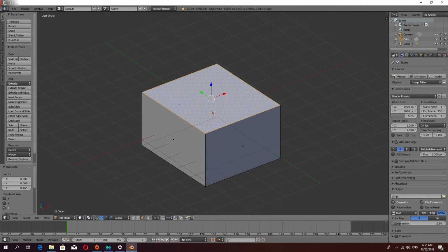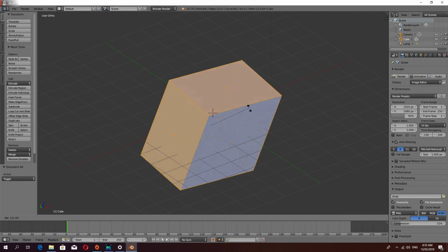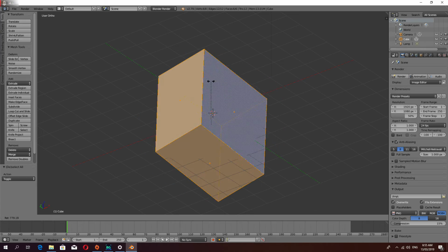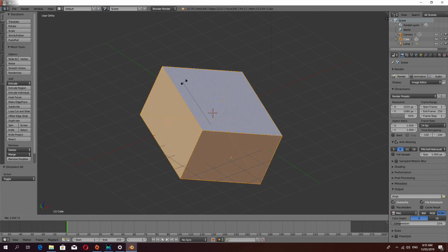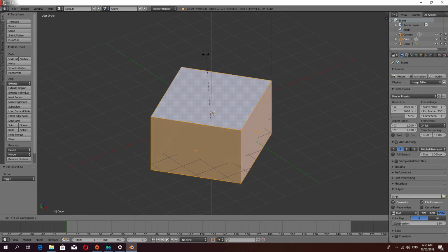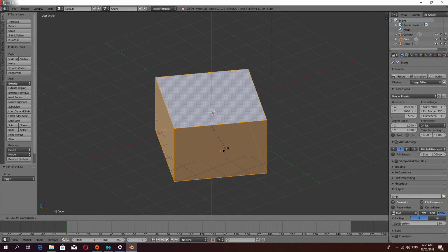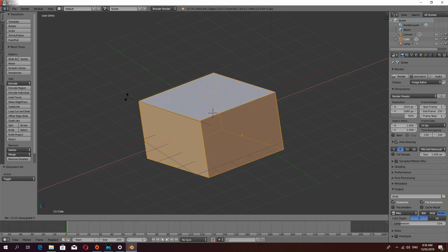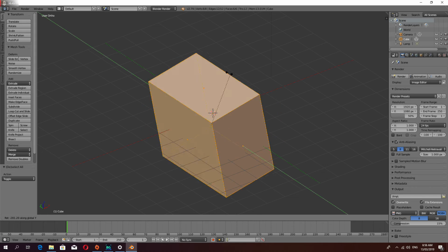And it's the same with rotation. Let's say I select the whole thing and I want to rotate. Rotate is R. Well, currently the rotation is kind of weird. It's done via the viewport, so it rotates it as though I'd stuck a skewer through the screen and I'm spinning the shape around. But if I lock it to the Z-axis, it's going to spin around that up-down axis. If I lock it to the X, it's going to spin around that X-axis, and the Y around that Y-axis.